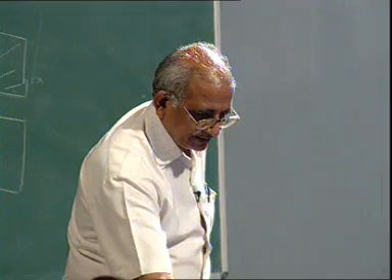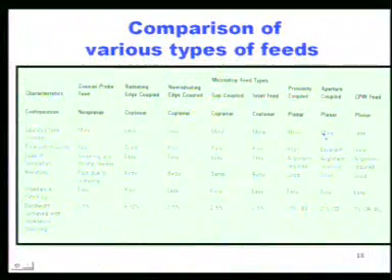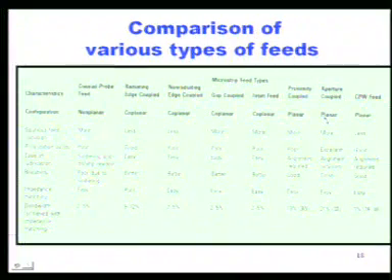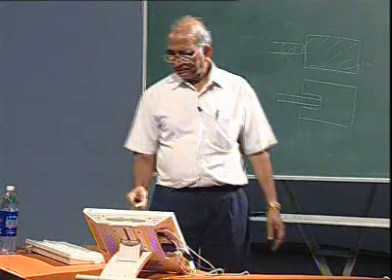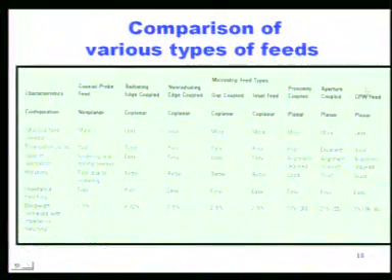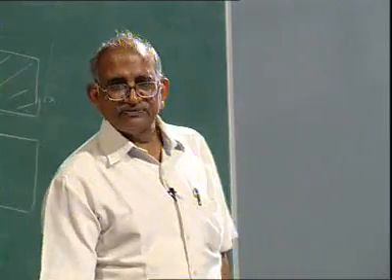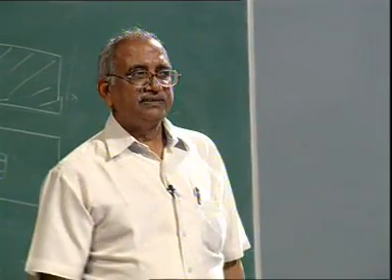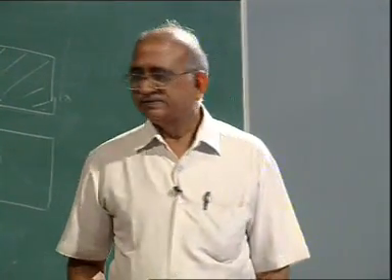Okay. Aperture coupled feed, again there is an open end over here, but fortunately this is on the other side of the ground plane and will not add to your radiation pattern. CPW feed, here the radiation is less. The reason is, in the case of CPW, CPW is a balanced line.